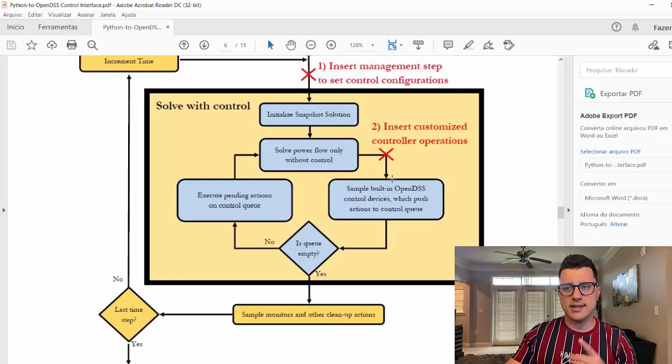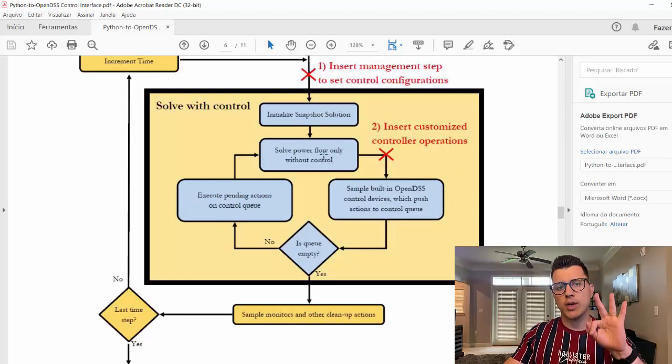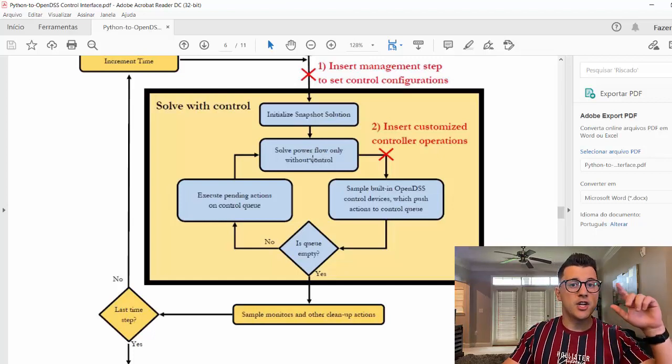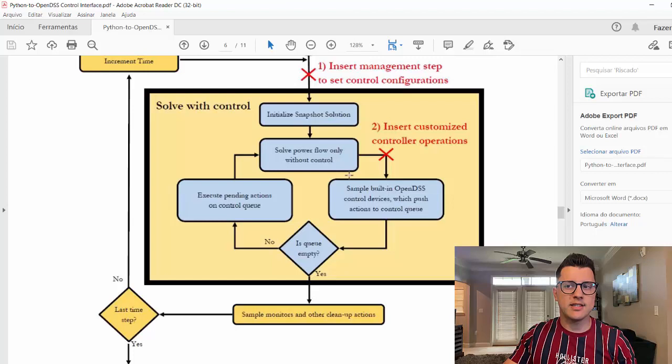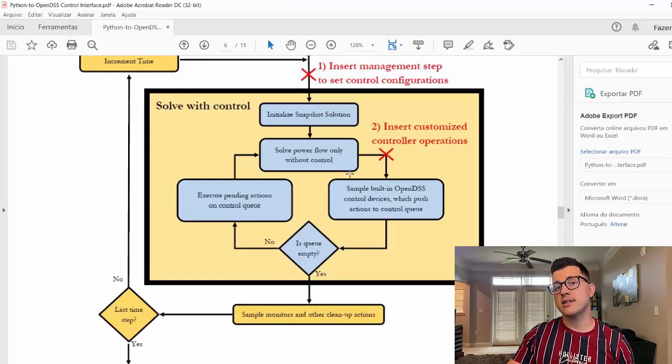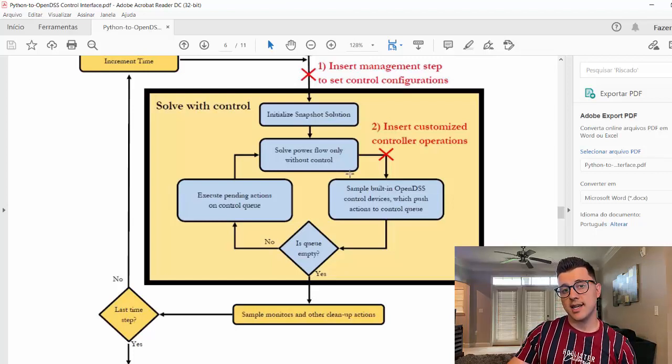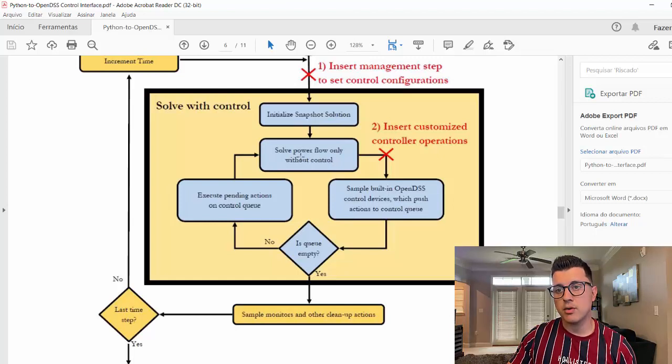You see that in this case, we performed 3 times the power flow. Each power flow has a number of iterations to converge. And these 3 power flows are, in another way, these 3 times that the regulator asked about the voltage he's interested in. I call that control loop. So we did 1 control loop, 1 power flow, control loop, power flow again for the second control loop, and power flow again for the third control loop.